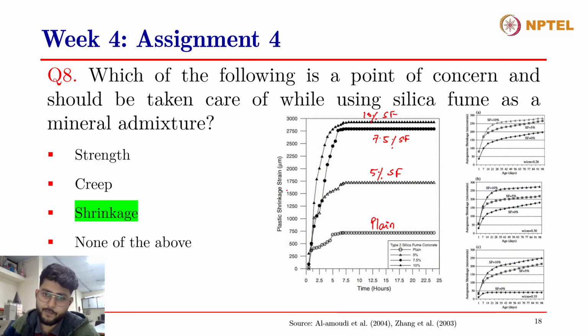And this is the plastic shrinkage strain in micrometer. It's a linear deformation that you're measuring, and this is the time in hours from the addition of water. And you can see that with the increase in amount of silica fume, the plastic shrinkage increases, right?